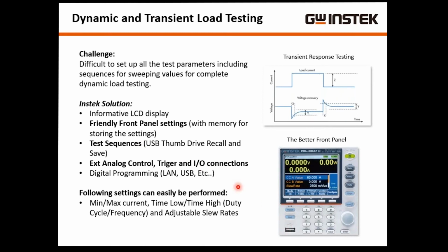You can just save it, look at it later, come back, and if you want to upload the actual program, you can do that as well. These electronic loads also allow for external analog control if you want to control it via voltage. There's a trigger, and we have a wide variety of interfaces as well: LAN, USB, GPIB, and some input-output connections.